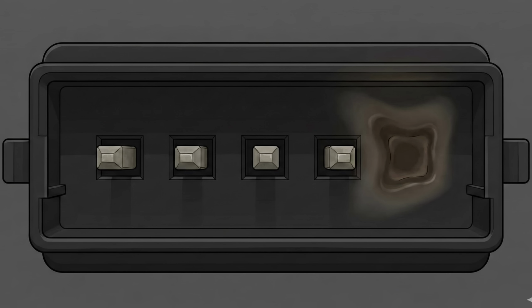And here's the number one failure I see all the time: a completely melted ground at a rear light. You've got no light operation at all, unlike our previous couple of images. We've got a completely blank light, nothing on the light works if it all shares a common ground, and essentially it needs a new lamp cluster, and crucially to replace the pin, because the pin spreading and arcing is what's caused this to overheat in the first place.